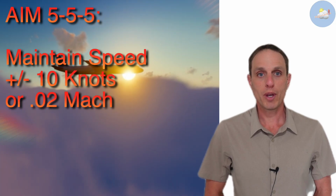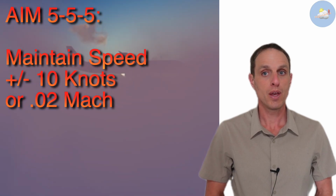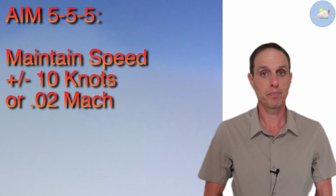As pilots receive speed instructions, what are the expectations for them to comply? Do pilots need to be spot on their assigned speeds? Pretty close. Per the Aeronautical Information Manual, pilots are expected to fly their assigned airspeed plus or minus 10 knots. If assigned a Mach number, then their assigned Mach number plus or minus 0.02 Mach.